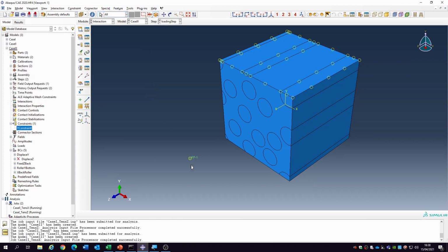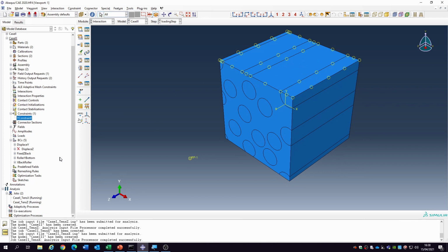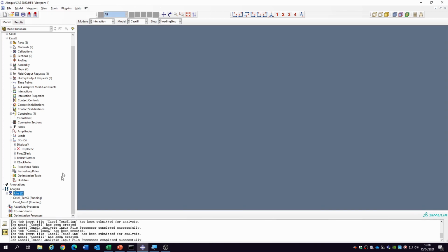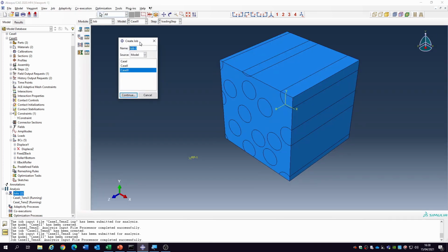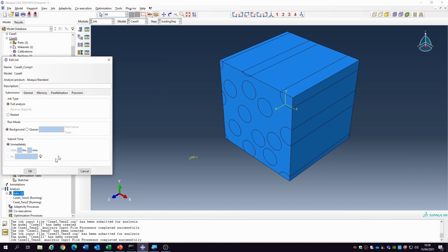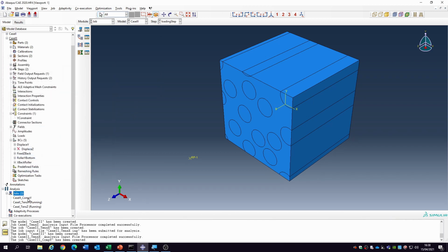So basically I'm pushing here, and then I'm tying it with kinematic constraints to that bit, and then that should really work. So while case 3 is selected, we name it case 3, compression Y, comp Y. Okay, so we'll submit that model as well.